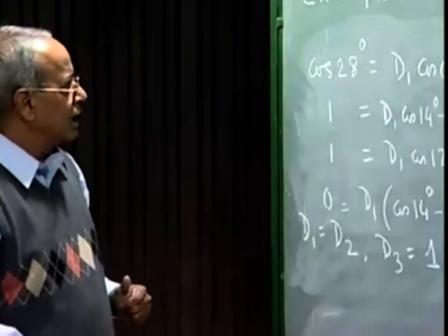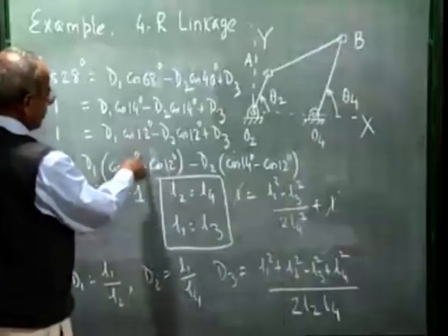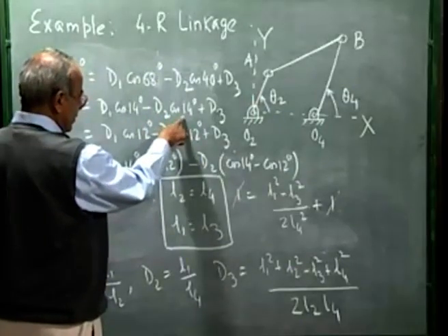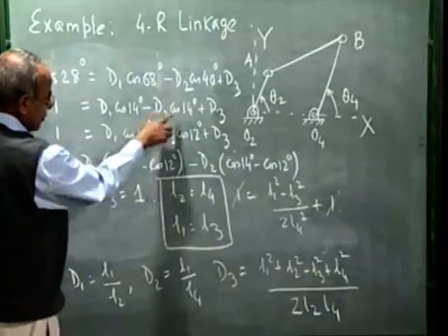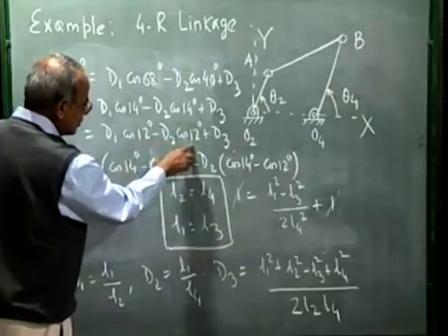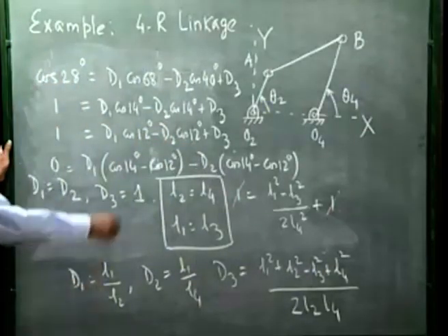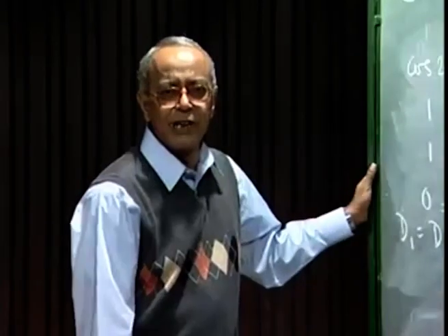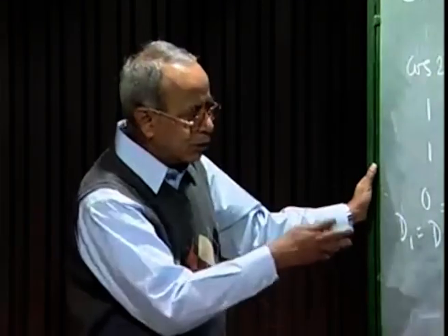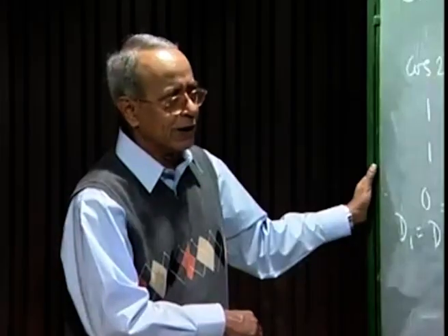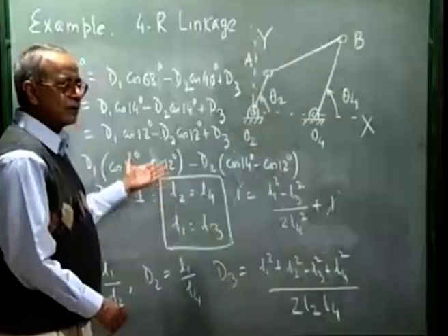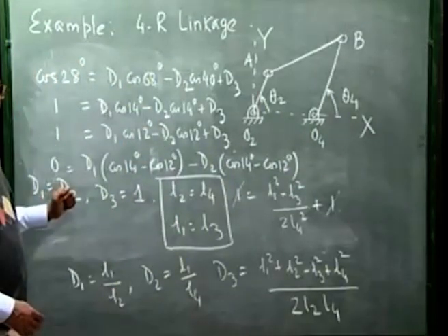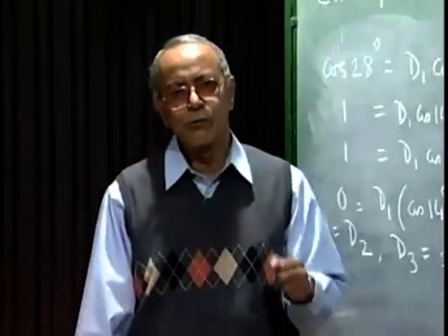It is obvious to note that 14 degree for both theta 2 and theta 4 can be taken up by a parallelogram configuration. Similarly, this minus 14 degree plus 12 degree will also be taken up by the parallelogram configuration, whereas minus 68 degree and minus 40 degree cannot be taken up by the parallelogram configuration, and we will see by the model that it will be taken up by the anti-parallelogram configuration, which means we have to go from the parallelogram to the anti-parallelogram branch to obtain all the three configurations. This we will now demonstrate with respect to a model.